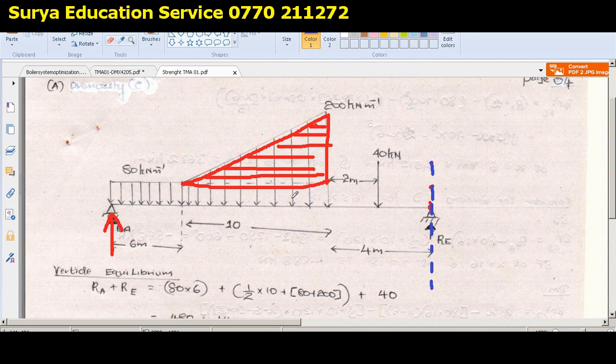So guys, just keep that in mind. In that case you need to know the centroid of the triangle. That is 1/3 of the height side. Now this is the height side, because here you have the height, right? Here, the non-height side, because here there is no height. So the center of gravity will act 1/3 from the height side.